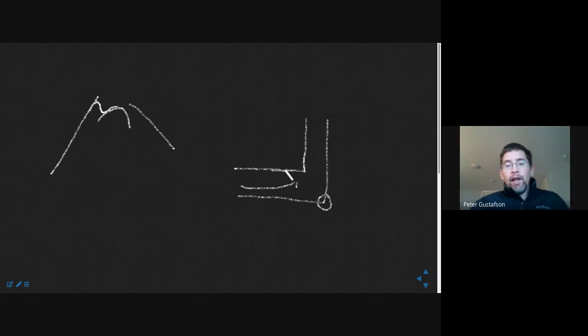Well, keep in mind that these structures don't come out of nowhere. They come out of real manufacturing facilities where in order to get this hat segment, they probably bent a hat segment out of flat sheet metal to begin with. So this is probably more realistically a rounded corner, something like that. This is more physically reasonable. And the more rounded that corner, the less stress concentration, the more it actually begins to look like what I've drawn here.